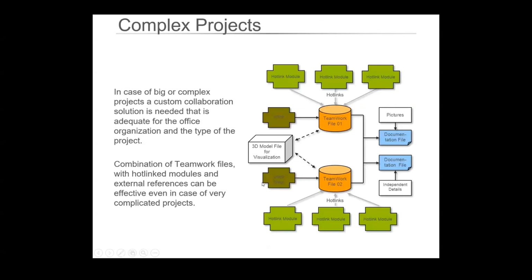So in the big projects, we tend to try and break it down. Like in Silta, for the Sasto file, we've got a Silpakeskus file, we've got a Podium file. I think we've actually got about 5 main files with lots of hotlink files into each of those. And then we have a master file where we bring it all back. And then we bring in XREF drawings, so this is DWGs from engineers, IFCs from the consultants, HVAC, stuff like that.